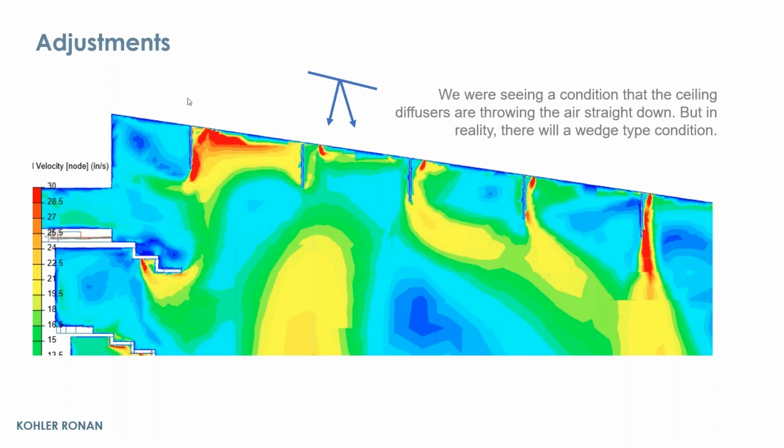And again, you start seeing really interesting conditions. You can see over here at the ceiling, we have these acoustical curtains that were falling. At some temperatures and airflows, air would cling to those curtains, and in some conditions it wouldn't. On the left, in the balcony side, we saw that the air was actually getting pulled out instead of going back inward. So we were able to change the throw angles of those as well.